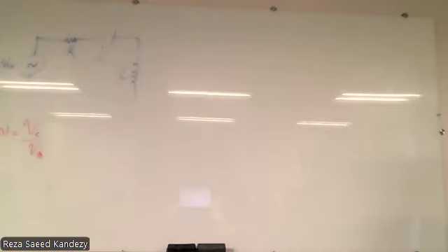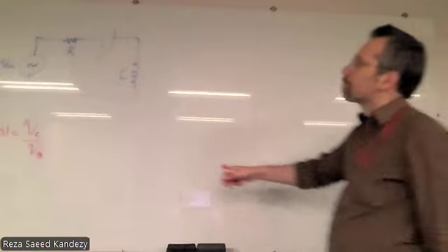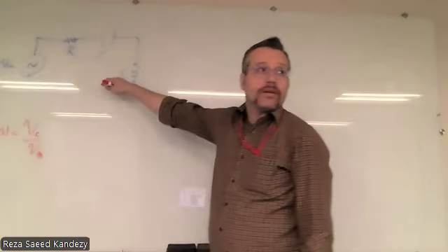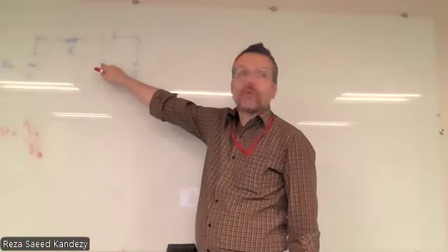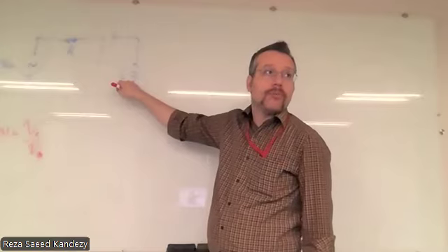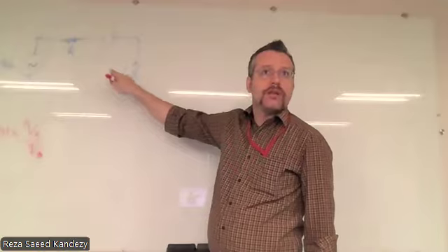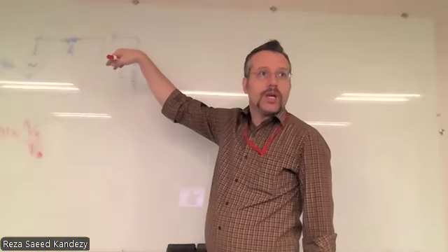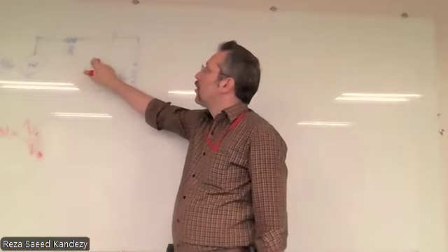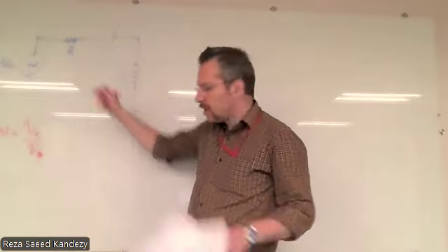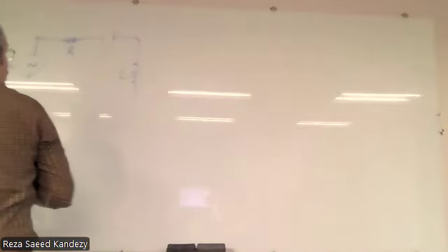Okay. And if we do that, basically, we have our S-domain circuit. So this one becomes 1 over CS. This one becomes LS. Okay, and you simply can run a KVL. So Vin is going to be R I plus 1 over CS I. Let me do that.